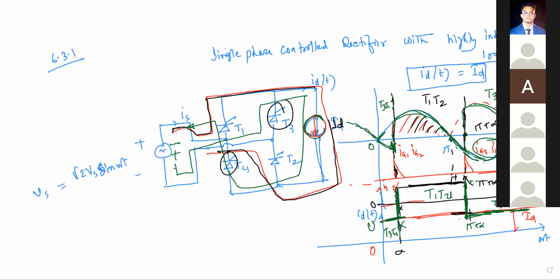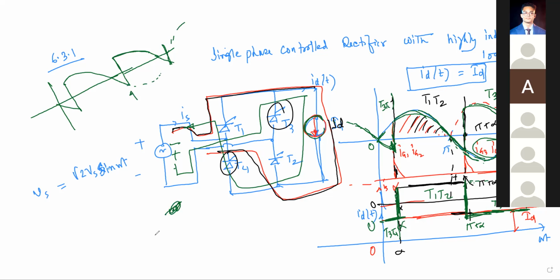Okay. So our output voltage wave shape will be like this. If you don't give the firing pulse here, then it will continue like this, and the input voltage will be your output voltage. You got my point? Our purpose of AC to DC will not be achieved. Yes, so with alpha we are controlling the output voltage, not the output current. Here the control parameter is the voltage, not the current. Current will always be constant.